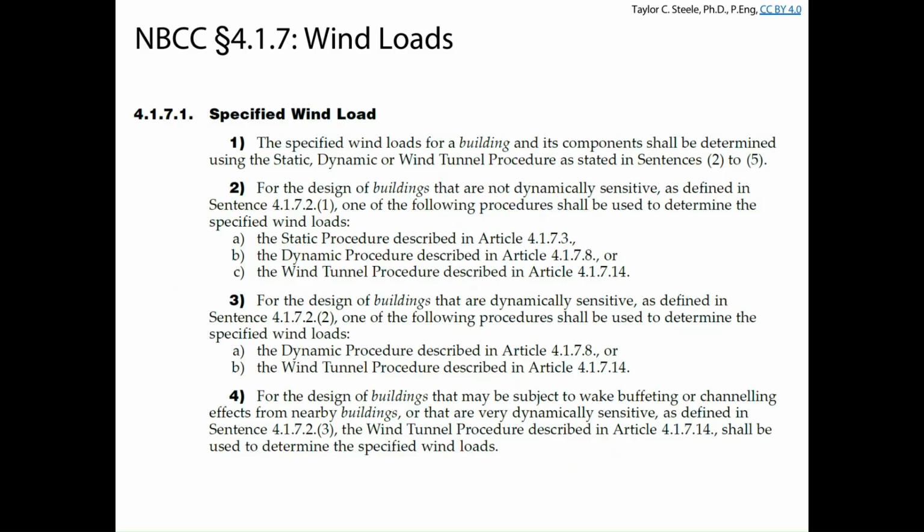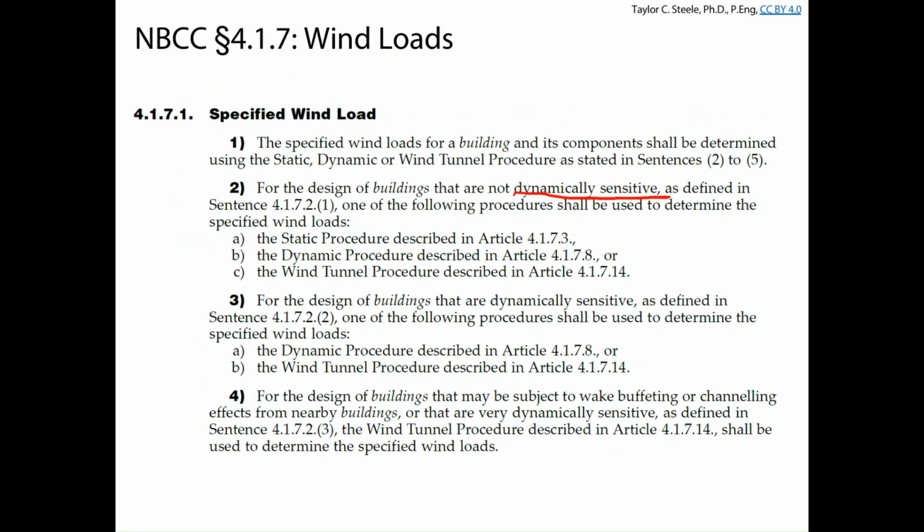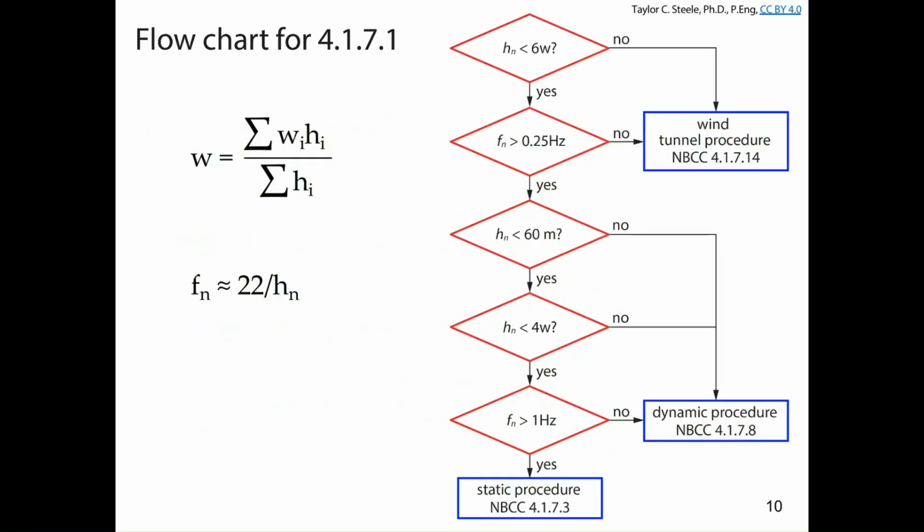So we've got this term dynamically sensitive, and that's a little bit difficult to figure out. What does dynamically sensitive mean? Well, basically, there are a couple of things that go into whether or not a structure is going to be dynamically sensitive. One of the things is: is the height of the structure going to be less than 6 times the effective width? For short, wide structures, they tend to not be very dynamically sensitive. And these are the widths here, the width of the building at each level.